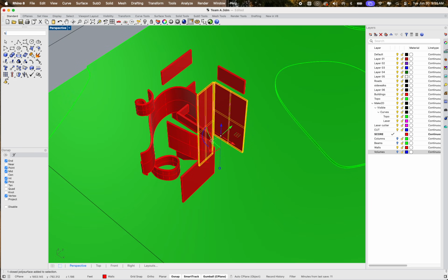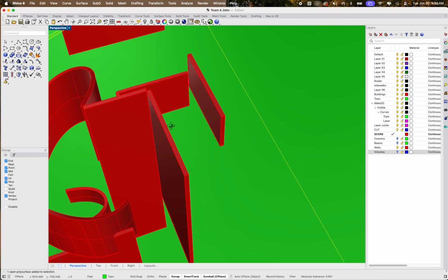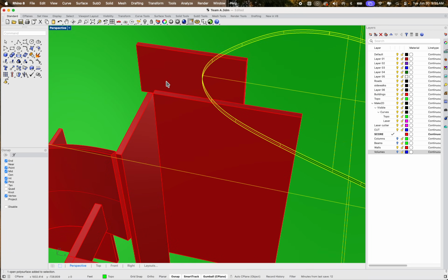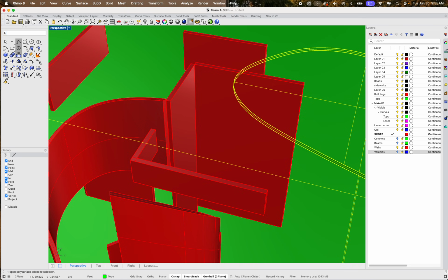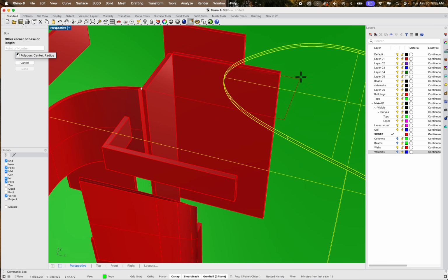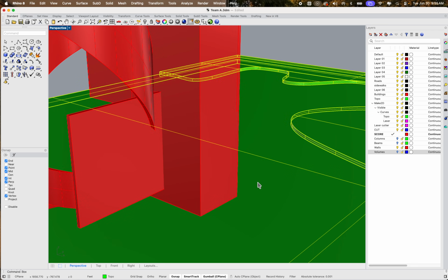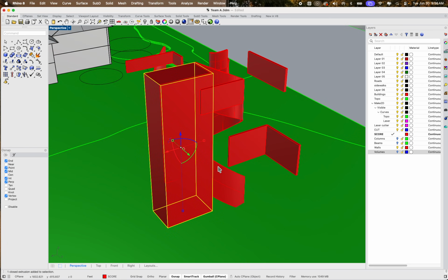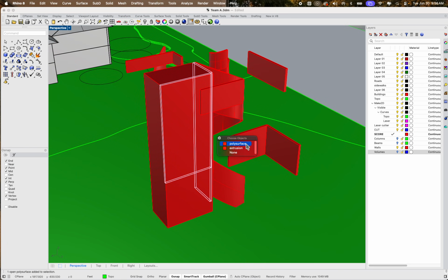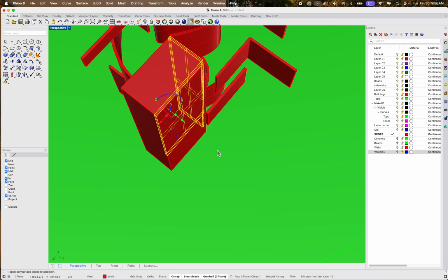In my case, I could start to Boolean union something, put them together, and perhaps make an entirely new shape out of it. So for instance, it's looking a little disjointed, and that's okay, right? Let's make it into something new. So for instance, I could take a box, typing in box, quite literally take 2 points and the extents of that box, and basically make a new box. And say maybe that's my vertical component. Maybe I start to even get rid of other components based on that, like I've already been influenced by this one, and maybe I even, I don't know, subtract from it or wire cut from it or what have you.